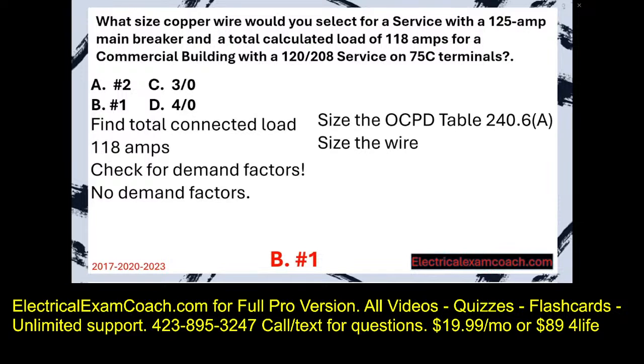In the testing center on the Electrical Exam Coach website, you'll have more variants of this and practice of this, but that's how easy it is with commercial. First, size the breaker based off the known load, and then you're going to size the wire. It really is that simple. Now let's dive into residential and learn a few more codes.